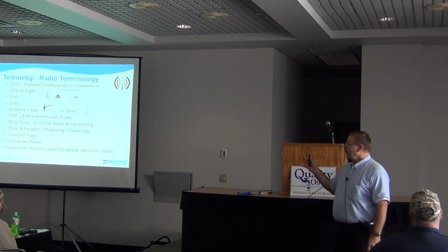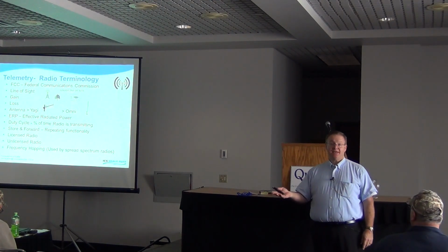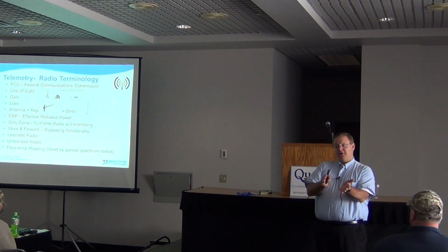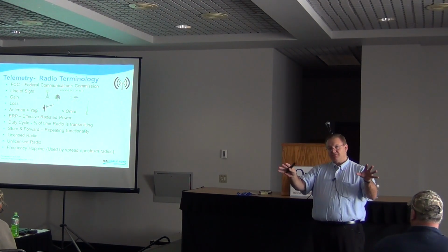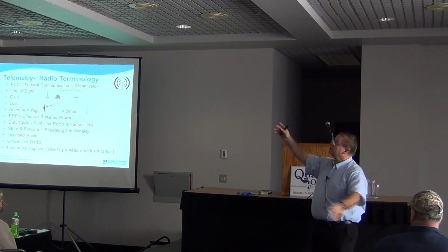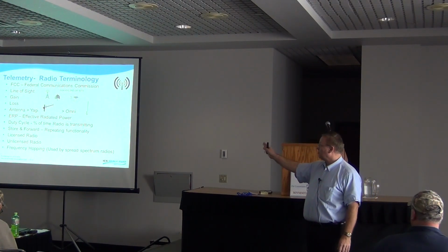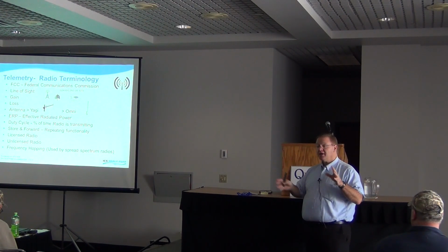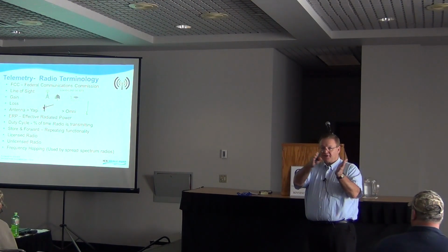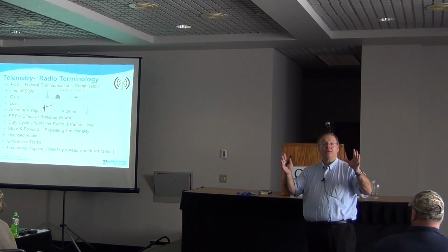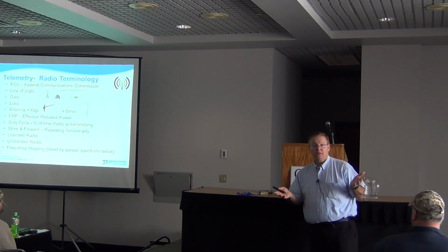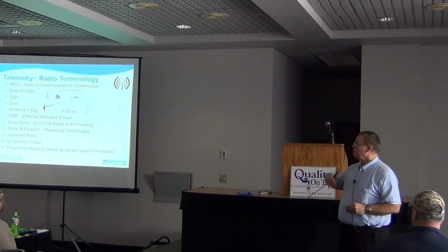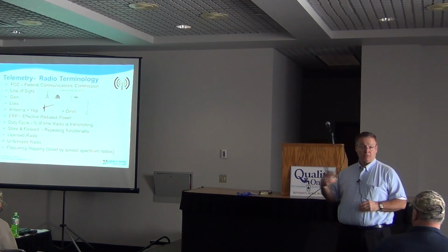So gain, that just simply says I'm focusing the energy on my radio system, my antenna. My antenna is constructed uniquely so that the energy that's emanating from it isn't going out in all directions equally. That would be more like an omni antenna, but you could do that. But with the gain, what it does is it focuses that energy. And if I can cut that radiation pattern down in half, I double my gain out to the area that I'm really trying to focus that energy to. And every time you have a 3 dB gain on your antenna, you're doubling your energy out there.